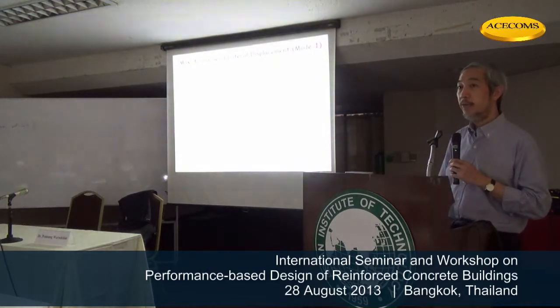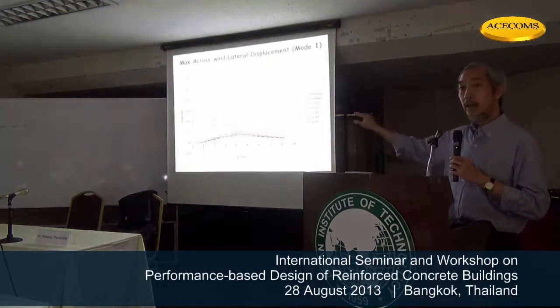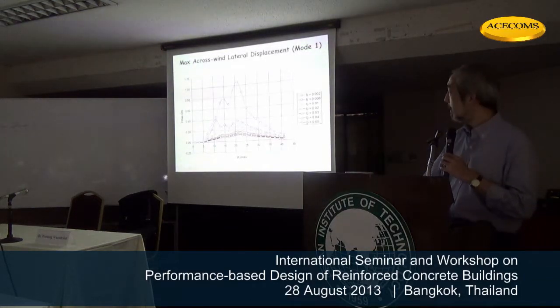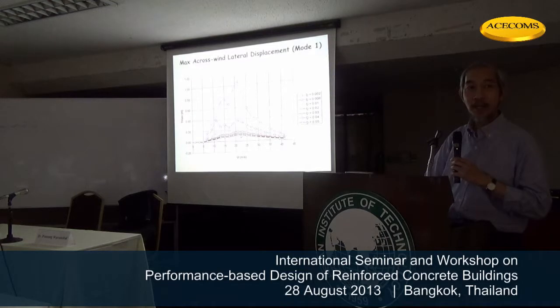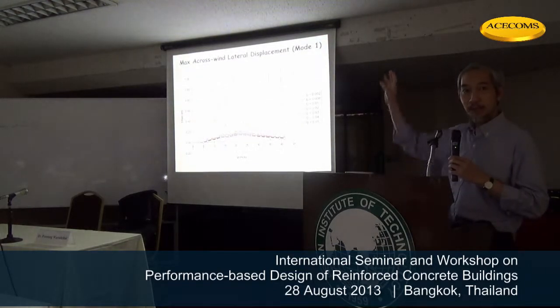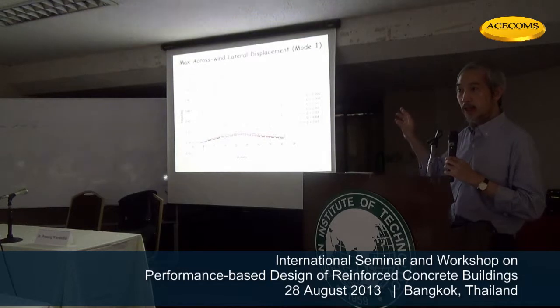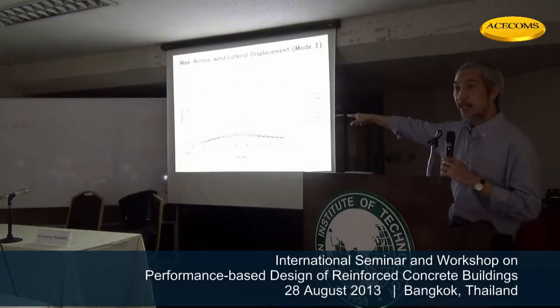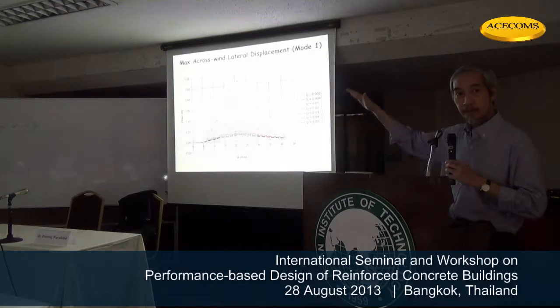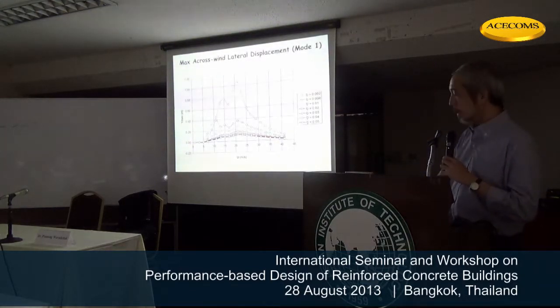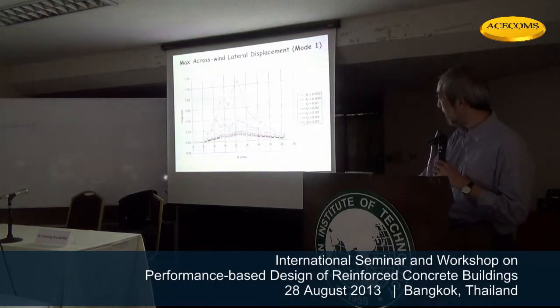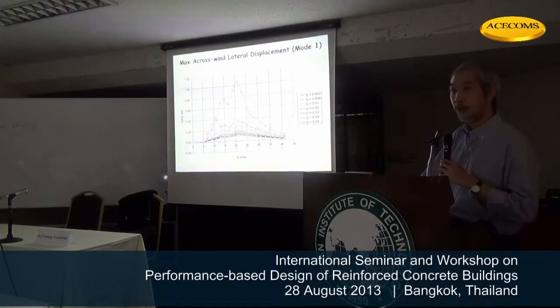But if we add a damper, if we reduce down to this, if you have 2% damping, 3%, 4, 5, 2 is okay, 3, 4, 5 are better. Okay, but with and without, you see the big difference. With a damper, it can guarantee that the amplitude will drop down to very low. So we then designed the damper to get about 4% or 5%. But if we achieve 2%, it is still good enough. Okay, that is the idea.